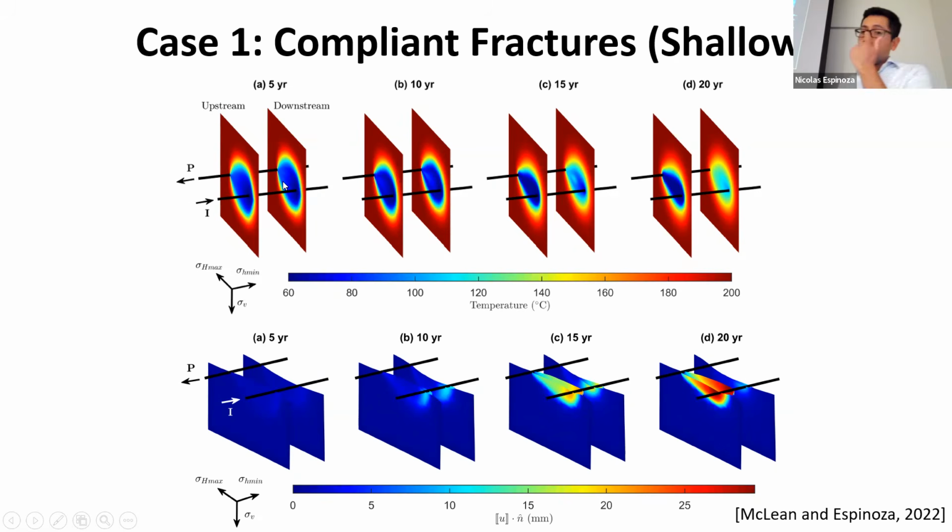What that means is that as we change stress, these fractures are going to open significantly, like several millimeters. So what happens is that we start at the beginning, here this temperature, and we are taking heat from the two fracture surfaces. And that's why this is blue, and this is the temperature of the working fluid. So this is low enough so that it's taking heat from the rock. So we're not seeing the rock here, right? The rock is transparent. We're just looking at the fractures.